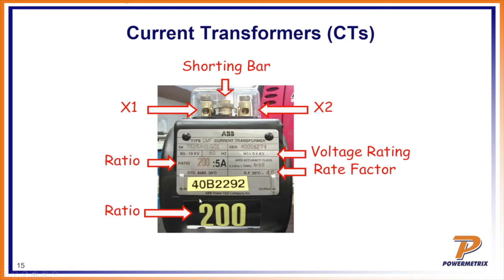If you were in my Guess the Metering Error class, you know that is not 100% true. We have seen it in some cases where the nameplate stamped on the CT does not match the actual CT itself. And that becomes a problem when they insert that into the site. And the only way to detect that is when you do an actual ratio test. And we'll talk about that in a second as well.